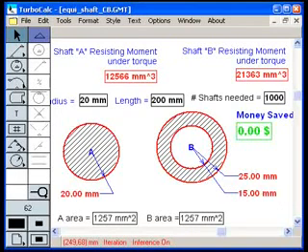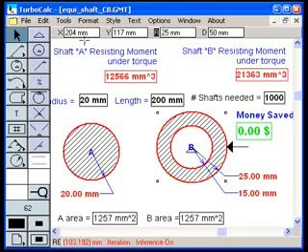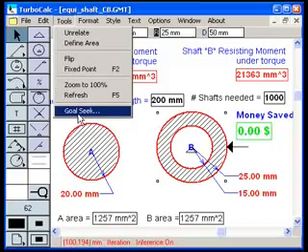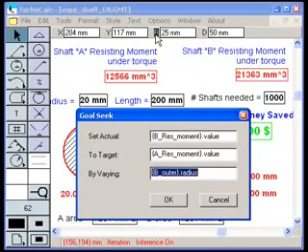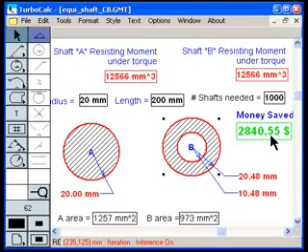And finally, the quick feedback from TurboCalc encourages users to perform what-if analysis of their engineering options. Here the user wants to know, what if a hollow shaft was used instead of a solid shaft here? So the shafts are made equal in strength by making the resisting moment under torque of the hollow shaft equal to the solid shaft by changing the outer radius of the hollow shaft. And in the process, the user finds this is the amount of money that will be saved when 1,000 shafts are used.